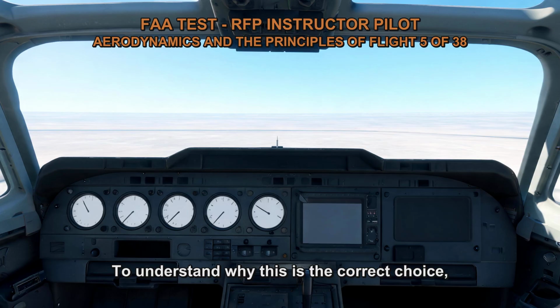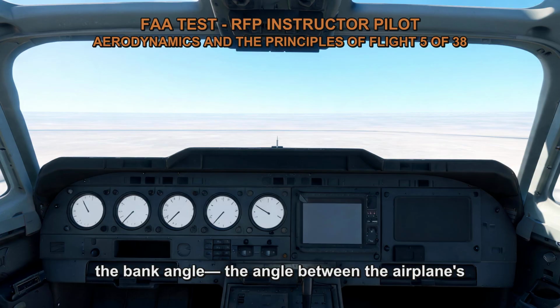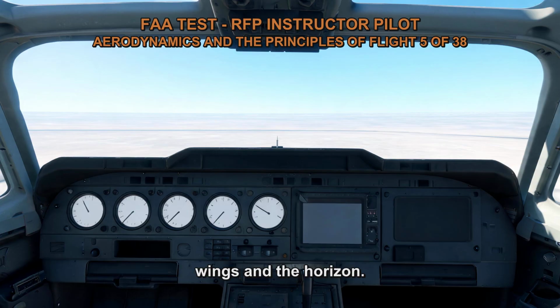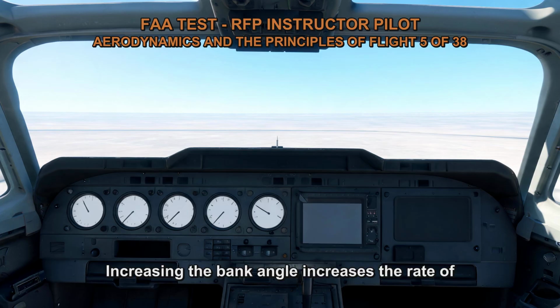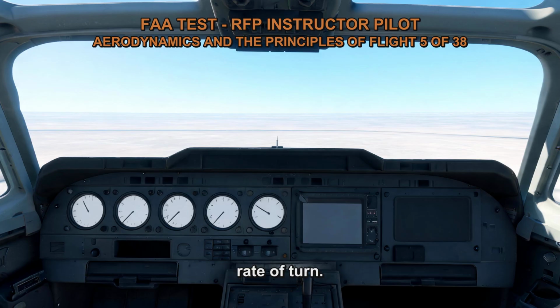To understand why this is the correct choice, let's consider the factors that affect the rate of turn and the radius of the turn in an airplane. The rate of turn is primarily influenced by the bank angle, the angle between the airplane's wings and the horizon. Increasing the bank angle increases the rate of turn, while decreasing the bank angle decreases the rate of turn. So, to increase the rate of turn, we need to steepen the bank angle.